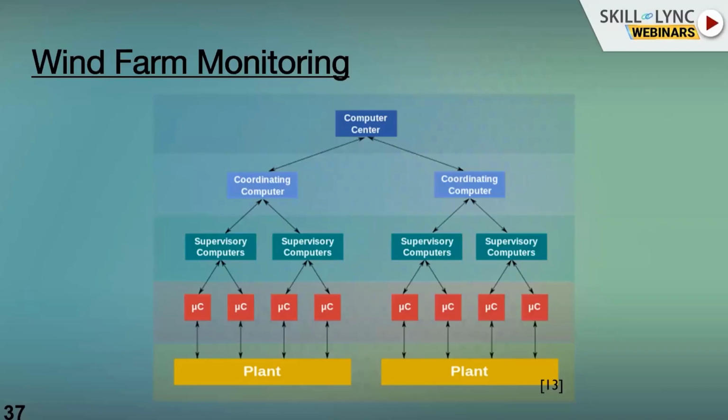And nowadays, each turbine uses nearly 150 to 200 sensors at various points. They will rectify the error at the monitoring station itself and try to run the turbines. The designer provides a set of instructions on what type of error or stoppage allows you to restart the turbine. For some stoppages, it is not possible to restart the turbine remotely. They have to inform the site person, who has to go and check and rectify the problem, and only then will they run the turbine. So this is the supervisory control SCADA system for the complete wind farm.